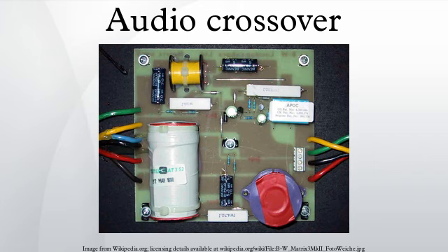Third-order filters have a 60 dB decade slope. These crossovers usually have Butterworth filter characteristics. Phase response is very good, the level sum being flat and in phase quadrature, similar to a first-order crossover. The polar response is asymmetric. In the original D'Appolito MTM arrangement, a symmetrical arrangement of drivers is used to create a symmetrical off-axis response when using third-order crossovers. Third-order acoustic crossovers are often built from first- or second-order filter circuits.